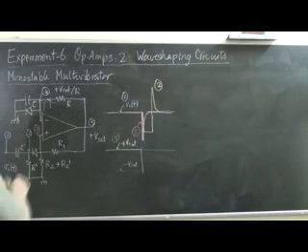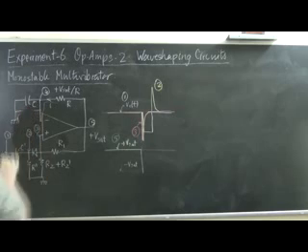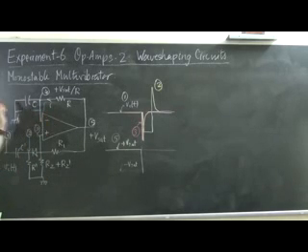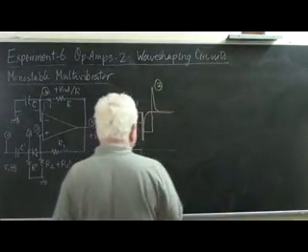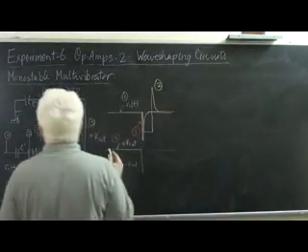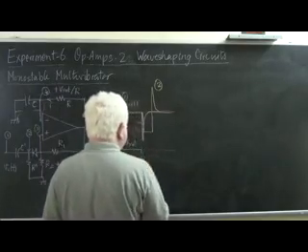That's as good as saying that we can take the diode out of the reckoning and just look at this as a capacitor charging through the resistor, C charging through R. So the capacitor, which was earlier at almost 0 volts, starts charging now towards this voltage of minus Vsat.